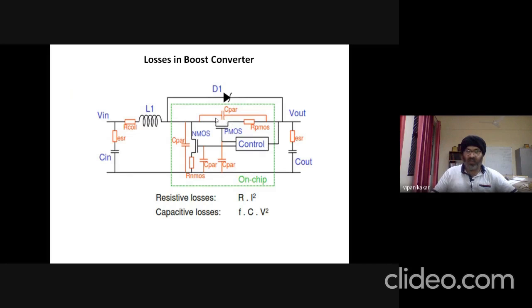But until now, we haven't discussed this PMOS switch. We were talking about switch S1, which is NMOS, and diode D1. This PMOS switch is normally used in industry or in practical circuits so that the efficiency becomes high, because PMOS switches have higher efficiency or better performance compared to lossy diodes. The losses in PMOS are almost negligible, and they can easily be synchronized.